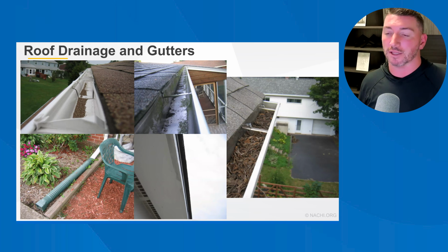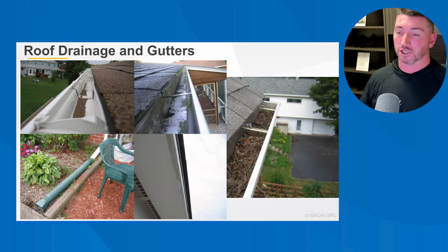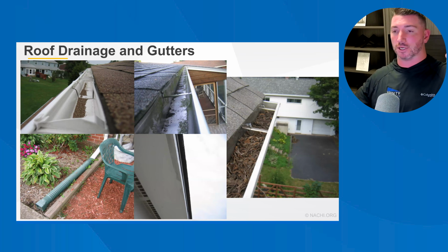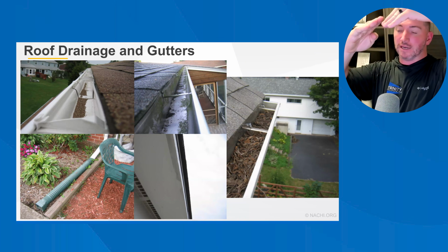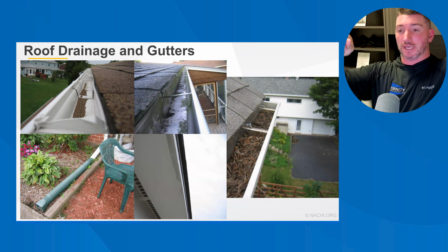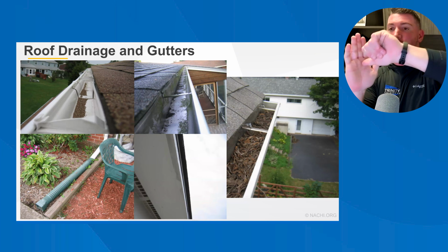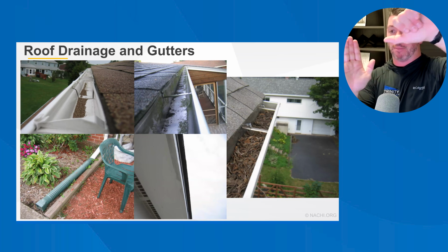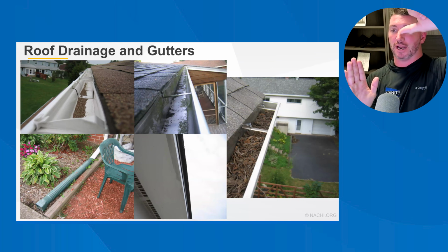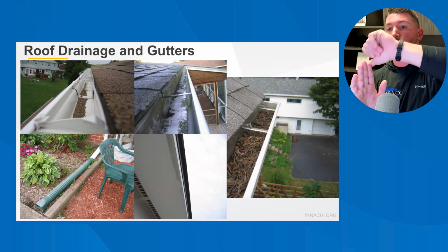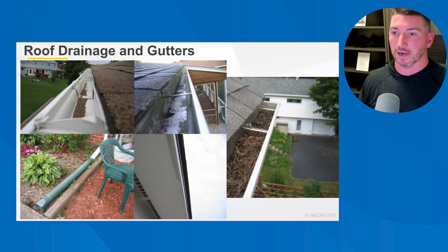One way to illustrate that would be if you have a level or any kind of a long straight thing, even a tape measure will function. Run it off the end of the roof. I like to use a level, where I can slide it down and it should hit the inside of the gutter, because that represents the water and where the water is going to be going. If it's installed so low on the fascia that I run something down the slope and it overshoots the lip of the gutter, well, then that's what the water is going to do when it's going at enough speed.